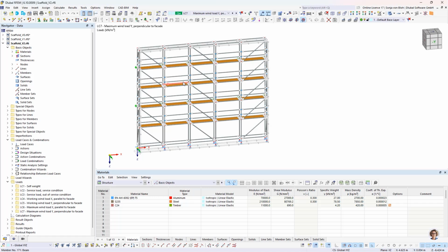In this webinar, I will concentrate on the ultimate limit state design of the standard. According to Eurocode 9, a second-order analysis considering the relevant imperfection is permitted. In this case, only cross-section checks are required, since stability effects are already captured by the analysis.